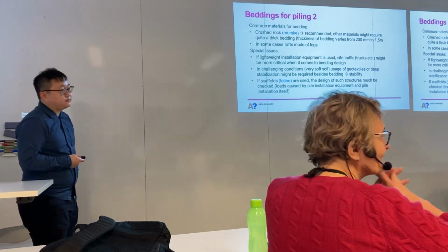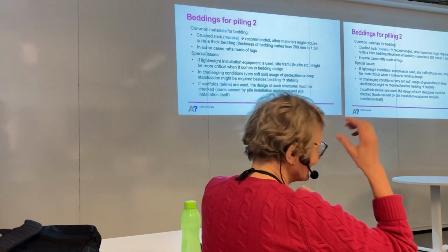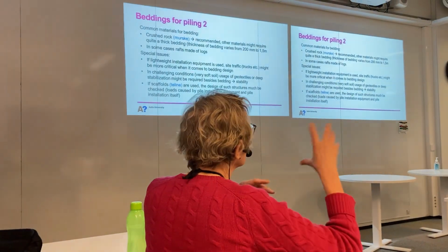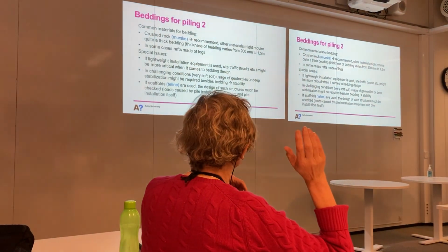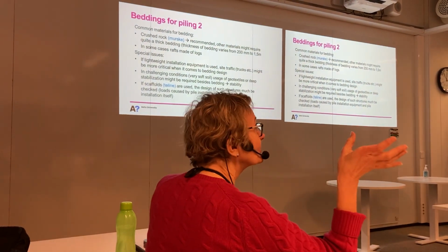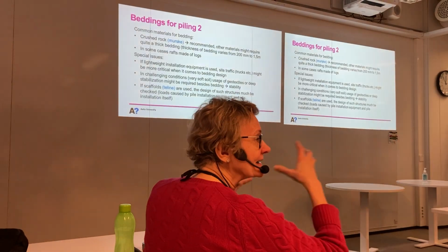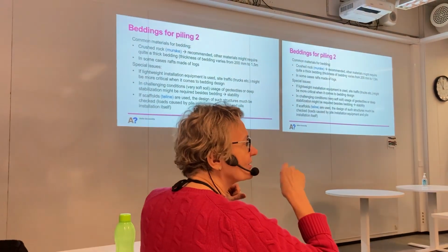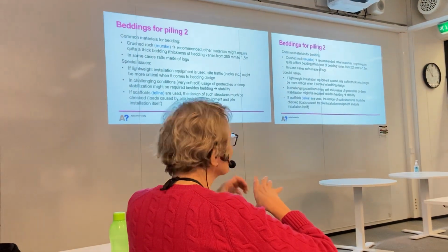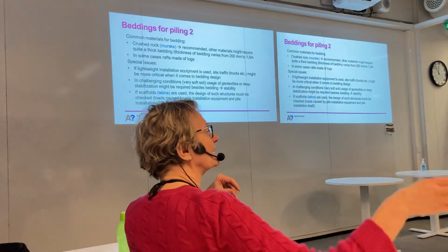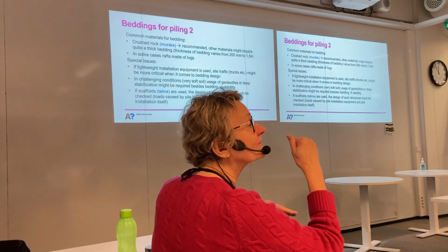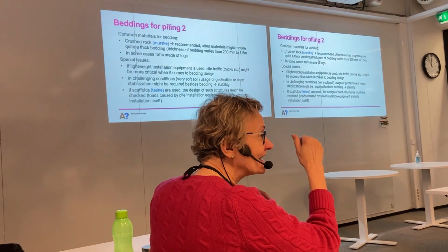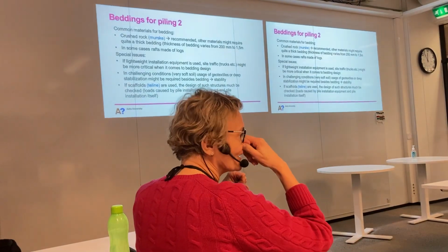May I interrupt here? Once again, one of my own experiences years back, on the road between Järvenpää and Lahti, there was a peat area where we needed to do piling. The contractor decided that instead of having this kind of padding, he took all the snow away and let the ground freeze, so you can also use freezing in this way to prepare the environment.